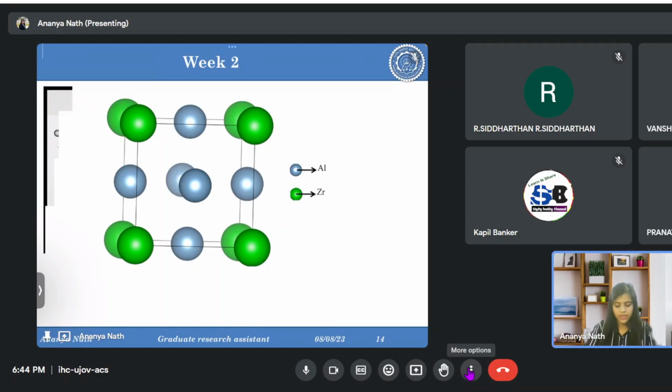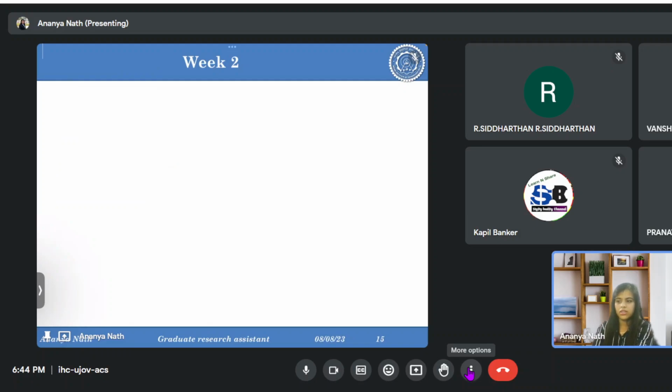So first of all, always remember if we are talking about a particular metal or a particular structure, here we are talking about aluminum metals. There are always dislocations present inside the metal alloys. They will always try to move inside the metal alloys, and if the dislocations move, it symbolizes the ductility inside the material. If we are giving a lot of force or stress to that particular metal alloy, the dislocations will start moving, and the ductility will be enhanced.